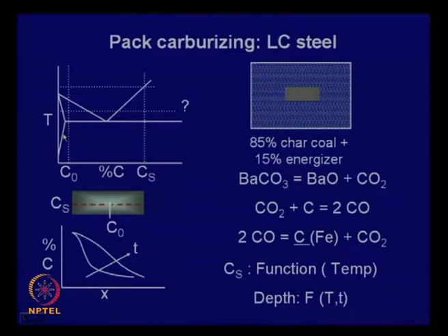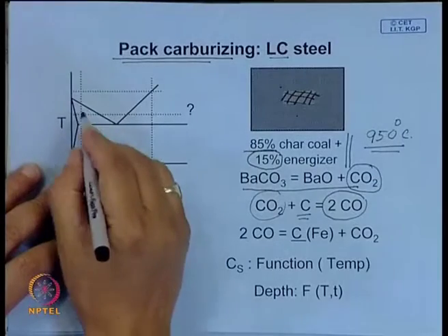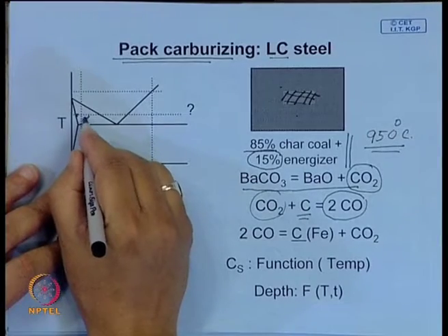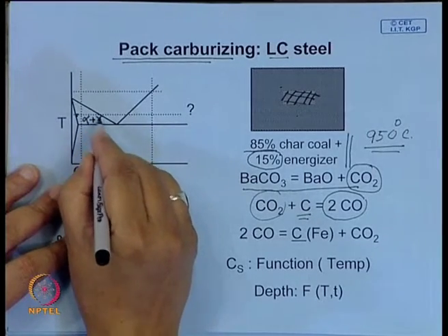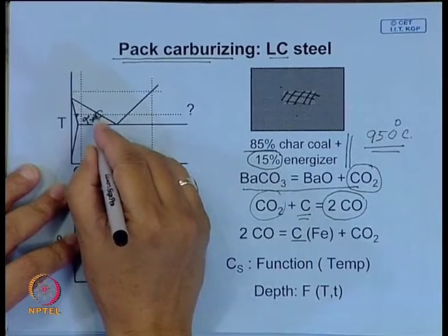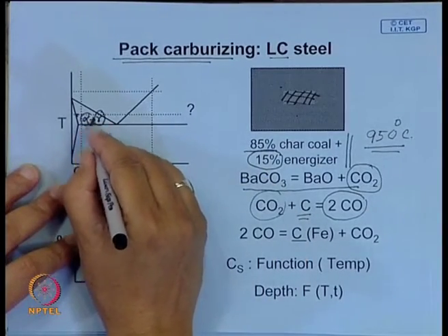So, this ferrite is saturated, so it cannot absorb much carbon. Now the question is, can you do a carburization over here? But the problem is that if you heat, it will be a two phase structure. At this temperature, the structure will be made up of ferrite plus austenite. Of course, austenite can dissolve a high amount of carbon, but not ferrite.